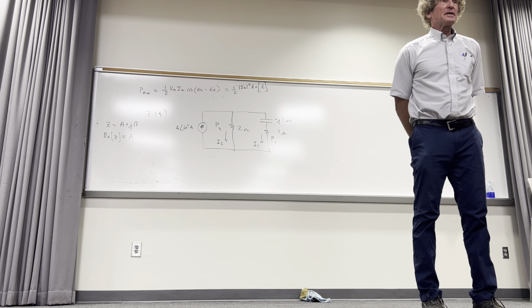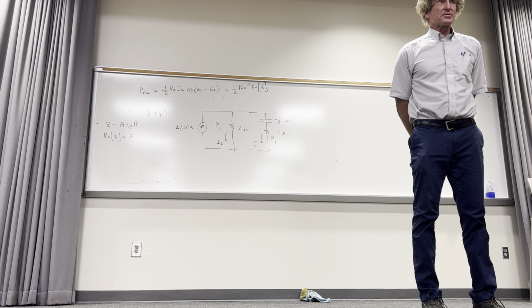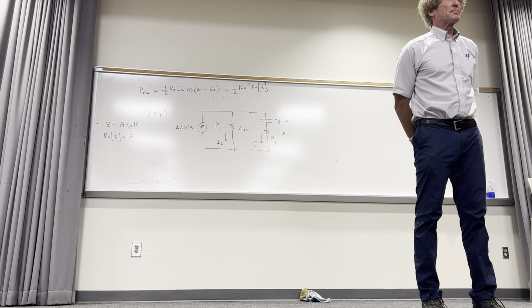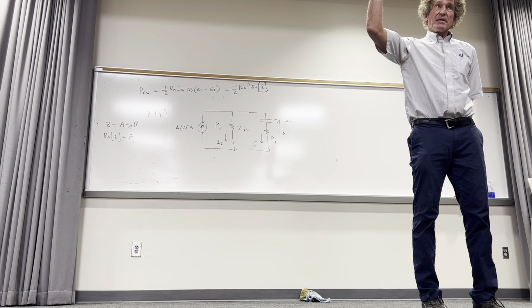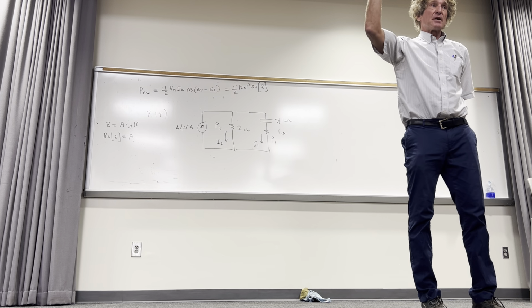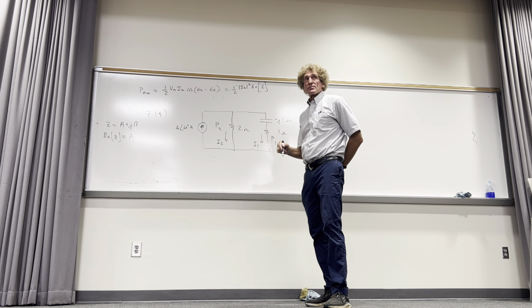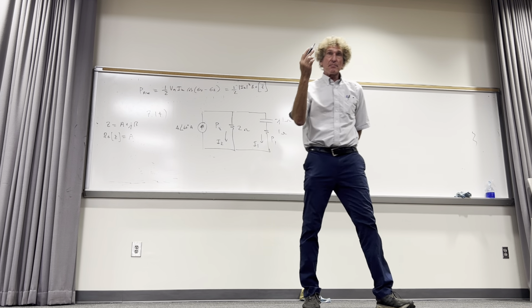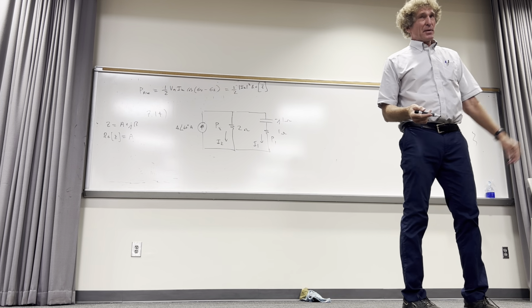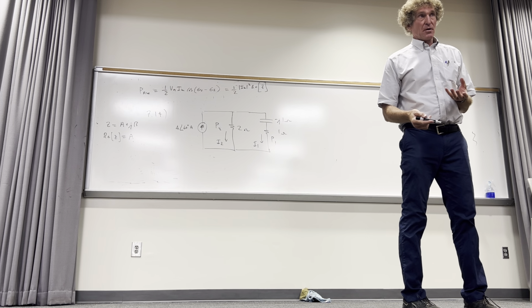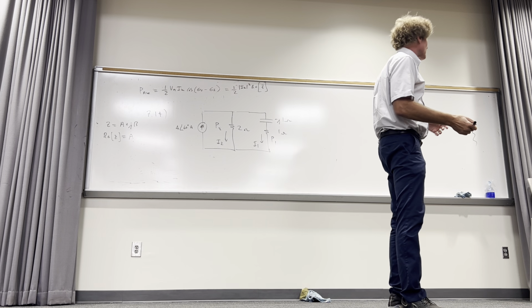I think current division would be the most straightforward method. You all see that you've got a current going into the parallel combination of 2 impedances. How many see that? I think current division would probably be the easiest. You don't have to do it that way. You can put a ground there, find the voltage there, then find the voltage and divide it by the impedances to get the current. But we already have the current. Why not just use that with current division?